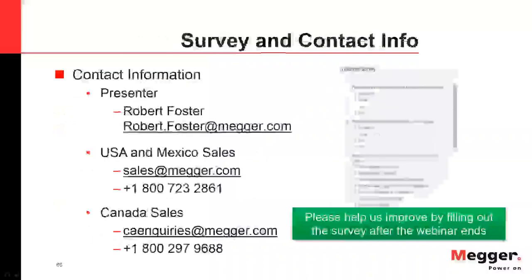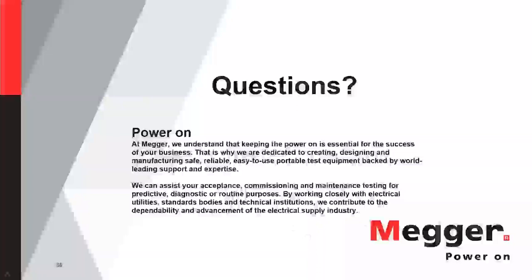I've seen where you use a linear transducer on a live tank and a linear transducer on a dead tank. I've seen people use a rotary transducer on a live tank and a rotary on a dead tank. It really just depends on the manufacturer. Look at that case study I did with Siemens. The manufacturer recommends using a linear, but we used the rotary and we were able to get very good results. So it doesn't really matter.